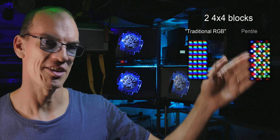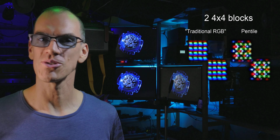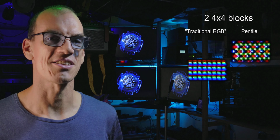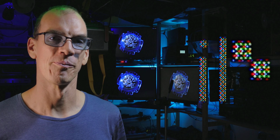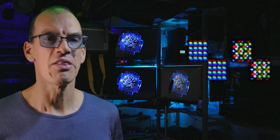Pentile displays tend to have fuzzier edges than non-pentile displays. This is because subpixel elements are shared between pixels, which means that the boundaries between one pixel and another are less clear, and they're also less consistent. So pentile displays rarely benefit from a higher resolution, so that these defects become less visible. So while edges may not be as defined as non-pentile displays, they do handle shapes really, really well. That's because they really thrive when there's lots of neighbouring pixels right beside each other, because then they can really optimize for that shape and keep it colour balanced and smooth.